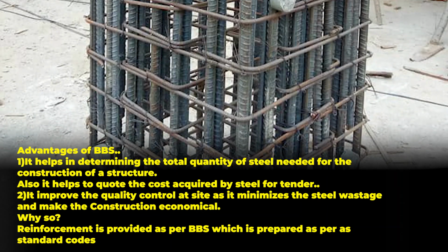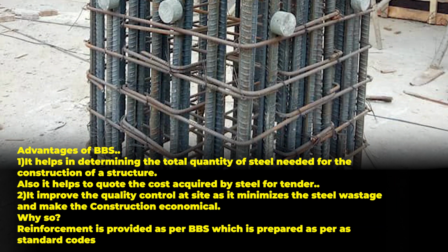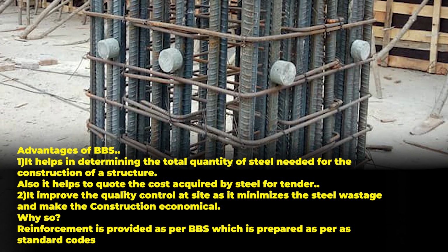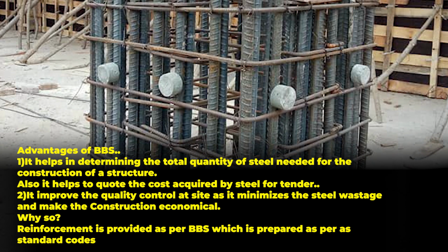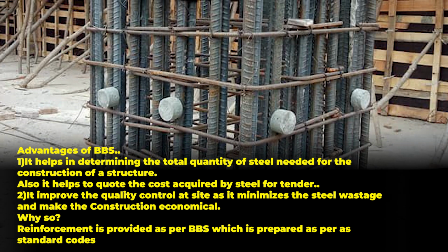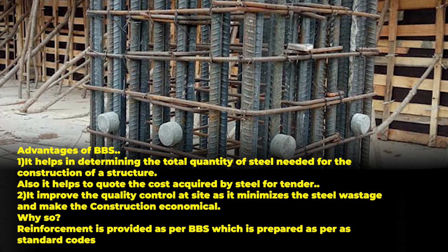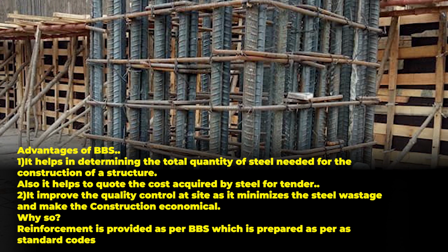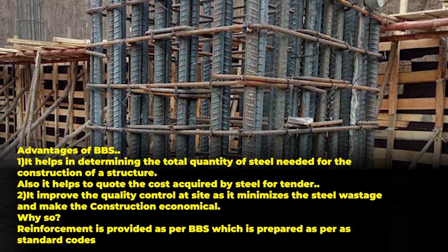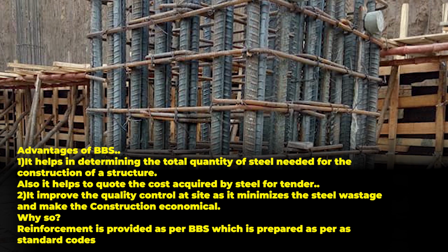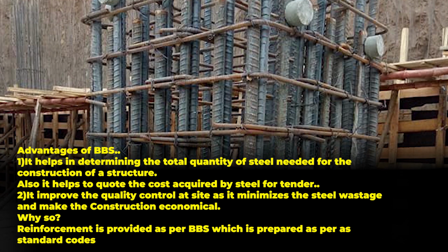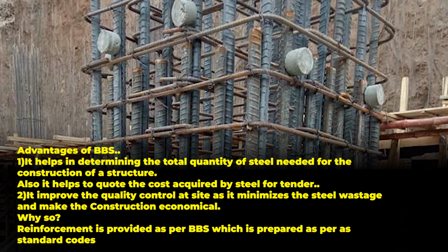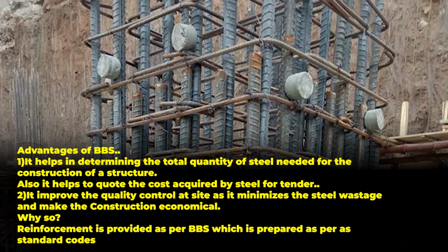Now let us understand its advantages. It helps to determine the total quantity of steel needed for the construction of a structure, and also helps to quote the cost incurred by the steel for tenders. It improves the quality control at site, minimizes the steel wastage and makes the construction economical. Why so? Because the reinforcement is provided as per the bar bending schedule, which is prepared as per the standard codes.